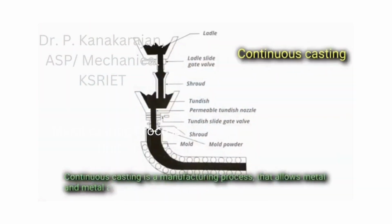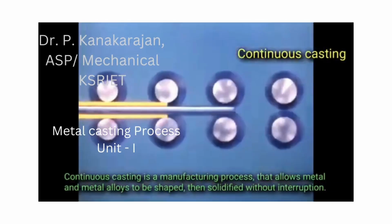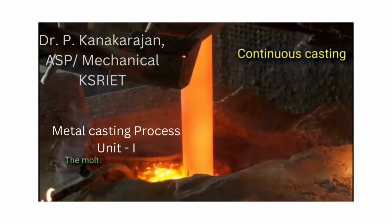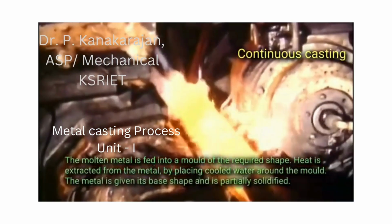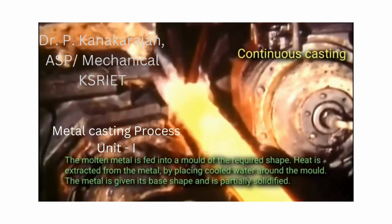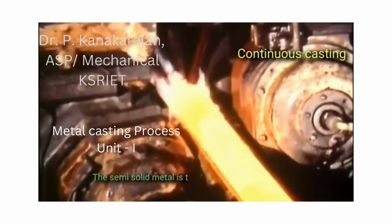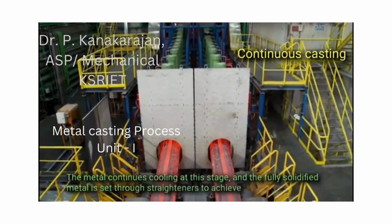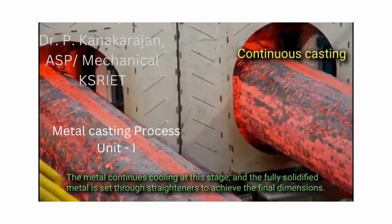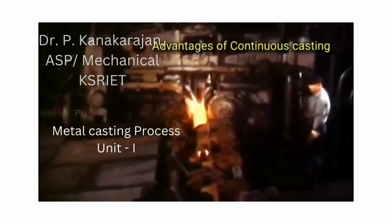Continuous casting is a manufacturing process that allows metals and metal alloys to be shaped, then solidified without interruption. The molten metal is fed into a mold of the required shape. Heat is extracted from the metal by placing cooled water around the mold. The metal is given its base shape and it's partially solidified. The semi-solid metal is then sent through a guide that will stretch the material to the required thickness. The metal continues cooling in this stage, and the fully solidified metal is sent through straighteners to achieve the final dimensions.